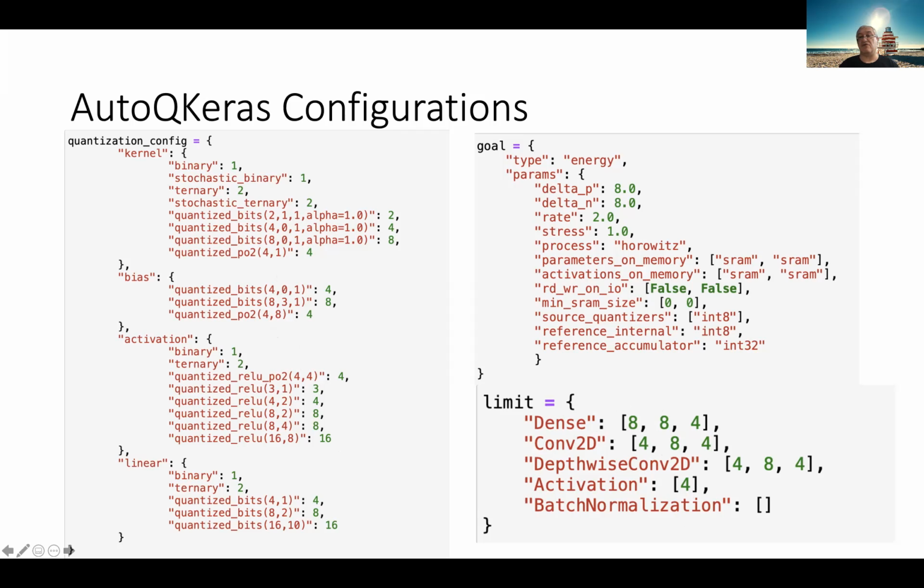Actually, we perform batch normalization in a very different way. We always compute the standard deviation using exponent quantization, and the gamma using exponent quantization, and the beta and the mean using exponent quantization, because then those operations can be made more compact and you don't have to perform multiplication and division.